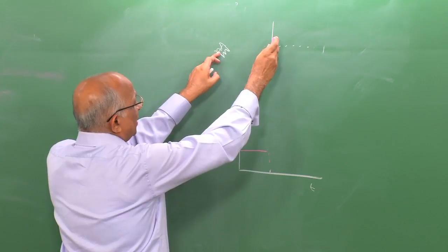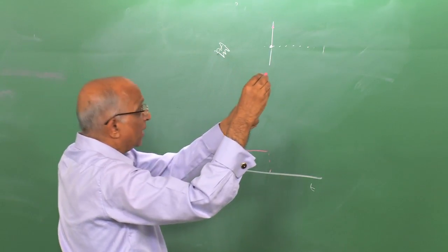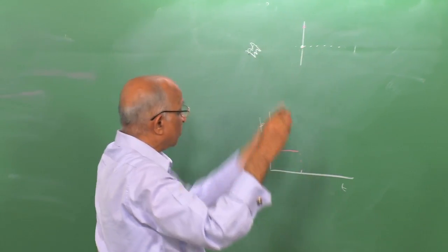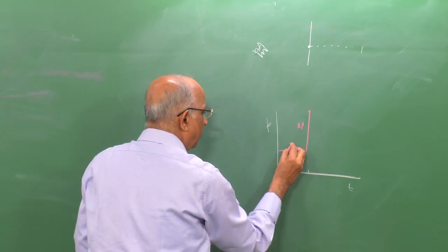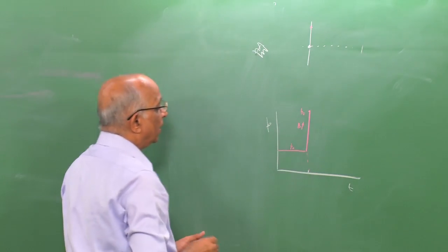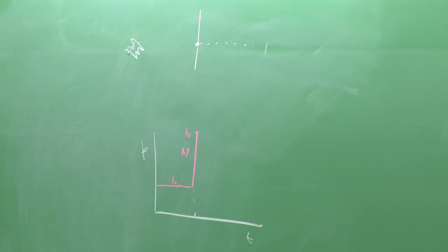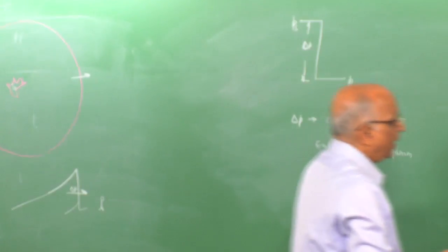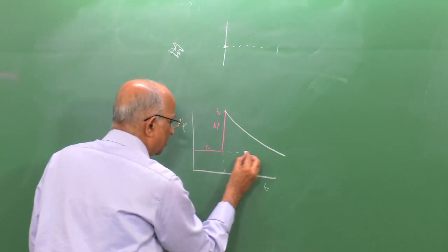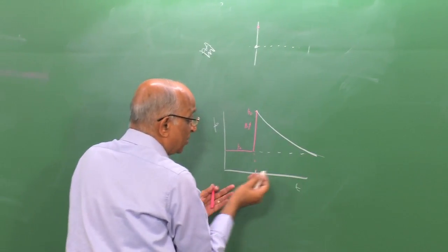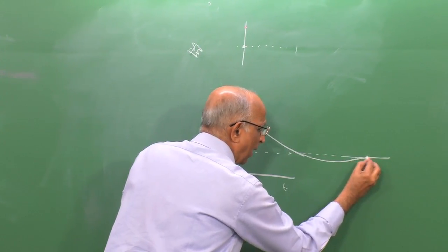After the explosion has happened, at maybe time t A, this wave comes at this particular point. I am focusing my attention on this point. When the shock comes over here, I get an overpressure which is delta P. The pressure rises from P0 to Ps, and as time progresses the wave travels further away. When the wave travels away, I am left with the rarefaction fan behind it, and therefore the pressure keeps falling. It may reach the ambient value, or if the momentum is sufficient, it can drag it and give rise to a negative value of pressure, but ultimately in long time I have this.